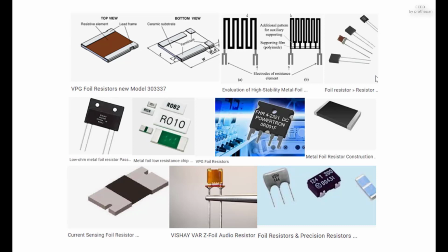Since their introduction in the 1960s, foil resistors have had the best precision and stability of any resistor available. One of the important parameters of stability is the temperature coefficient of resistance, TCR. The TCR of foil resistors is extremely low, and has been further improved over the years. One range of ultra-precision foil resistors offers a TCR of 0.14 ppm/degree C, tolerance plus or minus 0.005%, long-term stability, 1 year, 25 ppm, 3 years, 50 ppm, further improved 5-fold by hermetic sealing, stability under load, 2000 hours, 0.03%, thermal EMF 0.1 μV/degree C, noise 42 dB, voltage coefficient 0.1 ppm/V, inductance 0.08 μH, capacitance 0.5 pF.